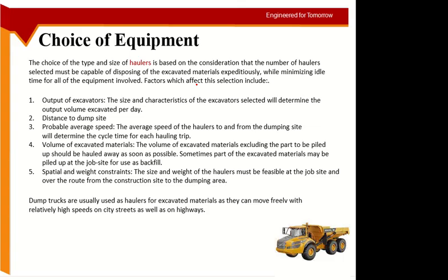Okay, so you want a bigger hauler because you have more material, but the size of the site is small. Now you may ask that if the size is small, why do I have more material? Okay, and this could be because you are going deeper. So it's a small site, but the excavation is deeper. So in that case, the quantity of material may still increase. Okay, so